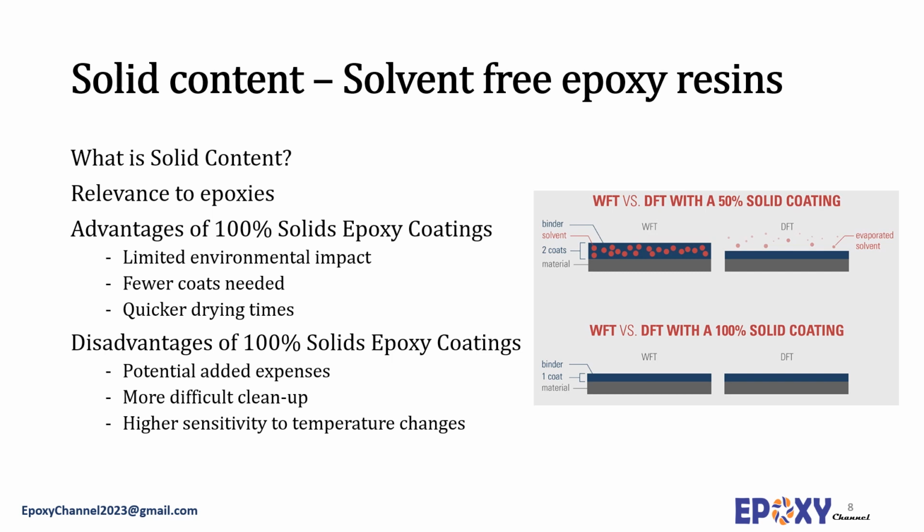Therefore, 100% solid epoxy resin suggests that the coating itself does not contain any water or solvent that could evaporate while curing. It will maintain 100% of its thickness, body and shape after the cure. Their wet film thickness, or WFT, is identical to their dry film thickness, DFT. The liquid in the epoxy will be identical to the epoxy that dries on whatever you are coating.